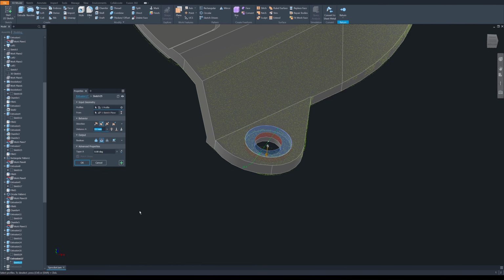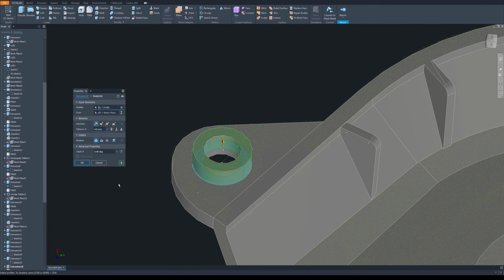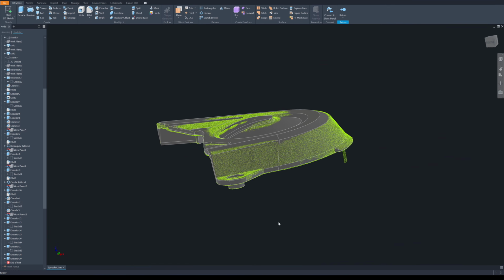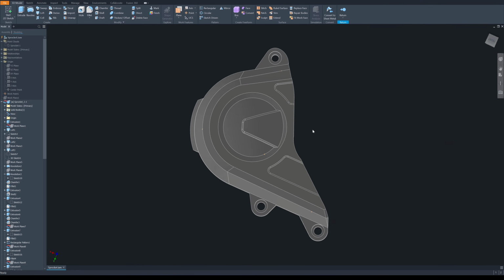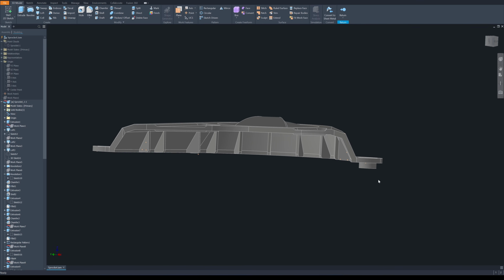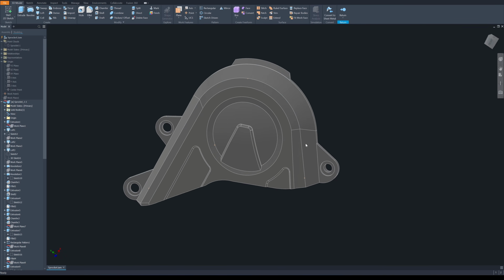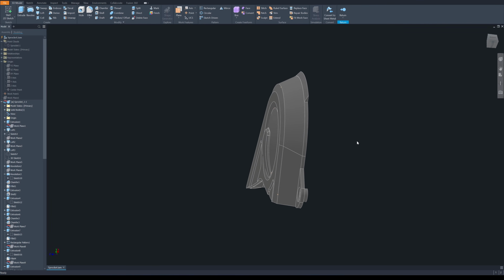Okay, they have an inset as well, and they have a spigot. It's an extrusion for the spigot. Okay, and now it's all done and should be ready for printing. If I print it like this, the spigot here is going to be a problem, and it requires support. So I print it like this in a vertical direction. I think this will give the best result.